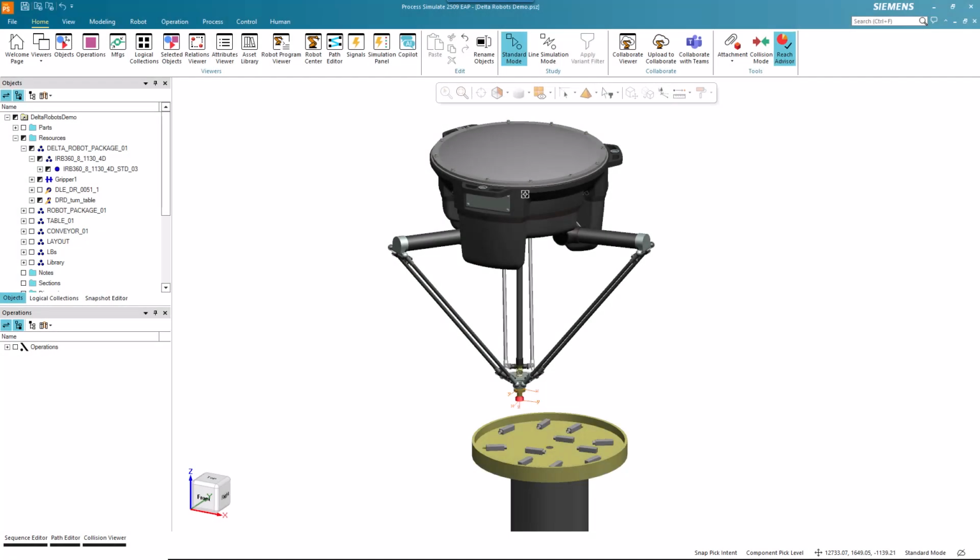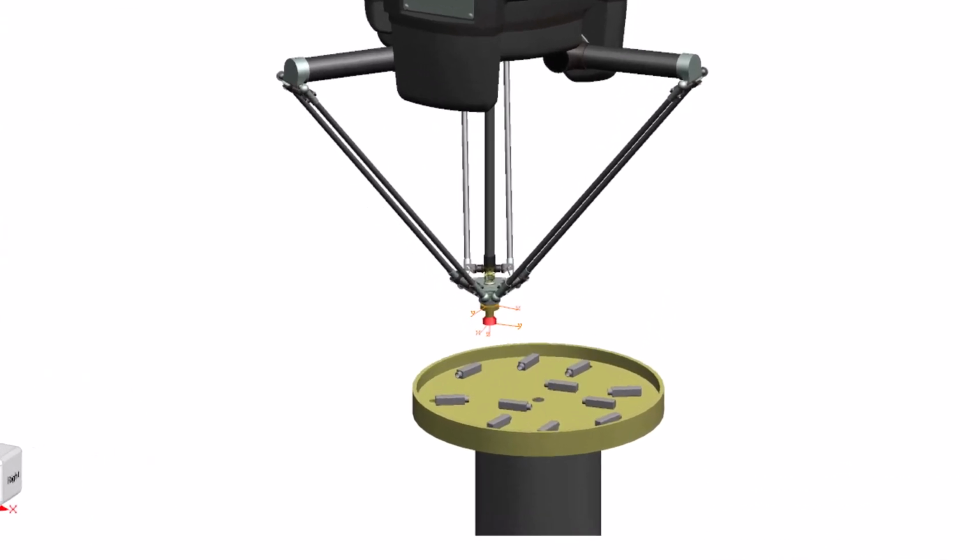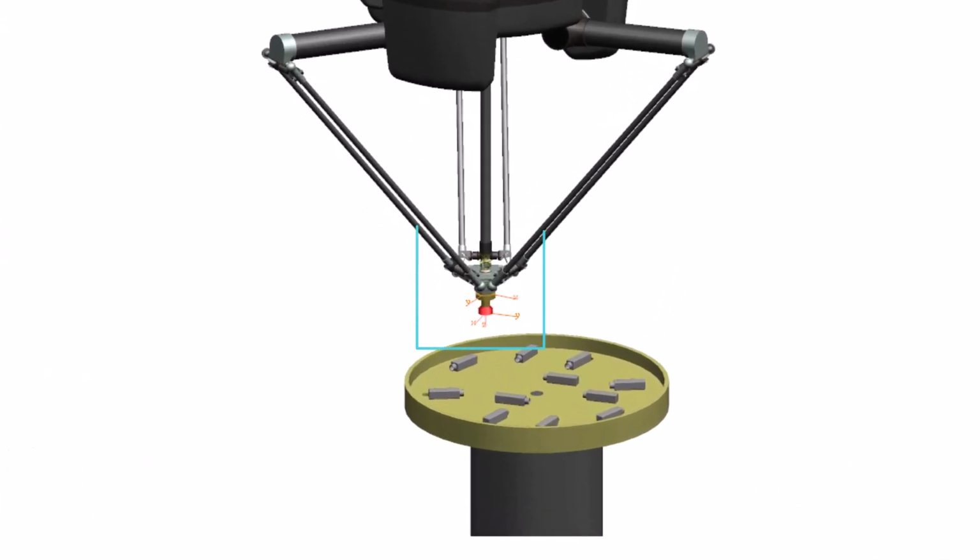Delta robots have 3 lightweight arms connected to a fixed base in a triangular Delta layout. The arm motors are mounted on the robot base. The additional central arm rotates the mounted tool. We have used the Mount Tool command to mount the suction gripper on the robot tool frame.